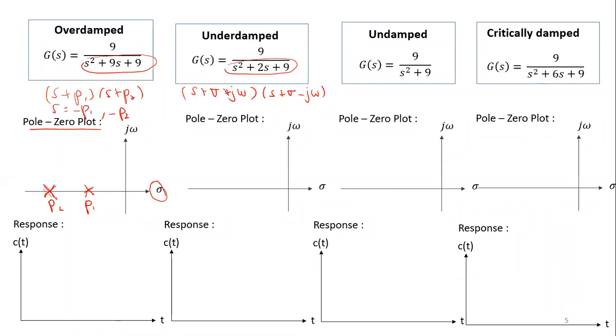When you get this kind of result, you know that this is an underdamped response. So the poles' location is plus here at the real part, the same real part, and minus here. Okay, so this is for underdamped response.